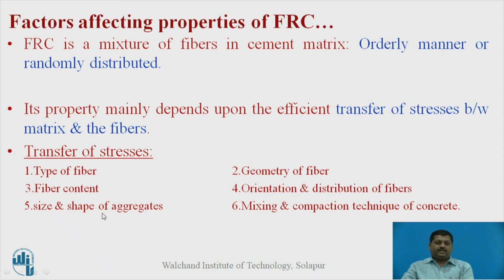And next is size and shape of the aggregate. Fifth point, which is an important point, because based on the size and shape, the cement matrix and its arrangement is dependent. And sixth is mixing and compaction technique of the concrete. So how the bond will develop between cement matrix and fiber, that depends upon this compaction.